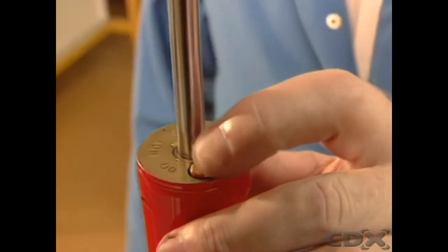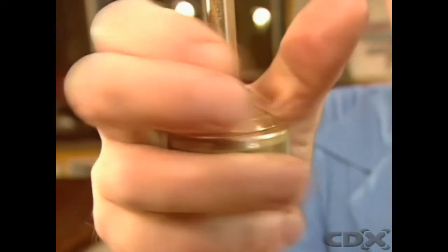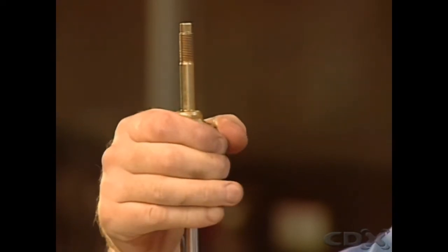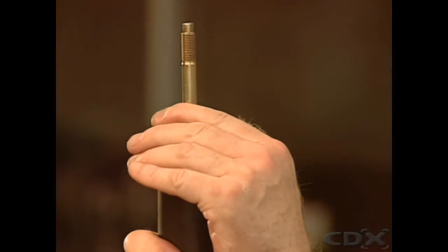On this shock absorber, when it's extended to its maximum length, a pin is depressed, locking in an adjustable slide on the piston assembly. Twisting the two halves of the shock absorber changes the number of orifices and the spring force on the valves.